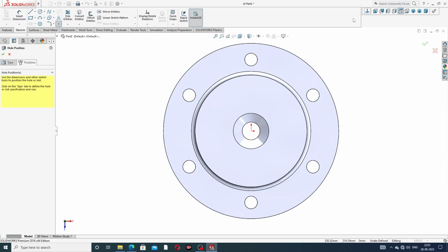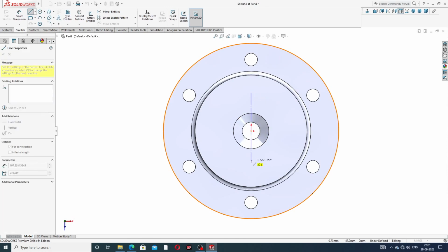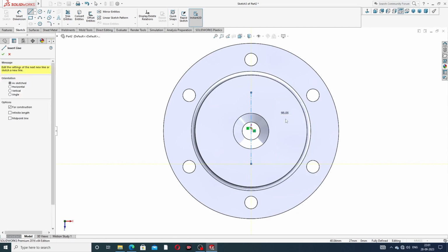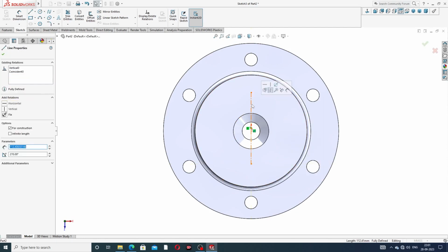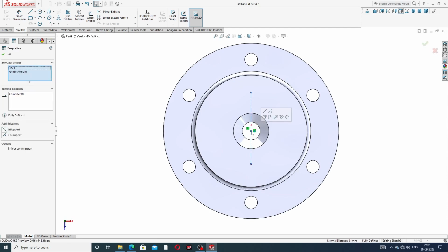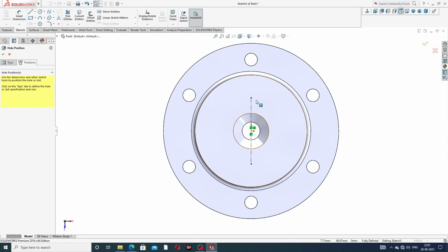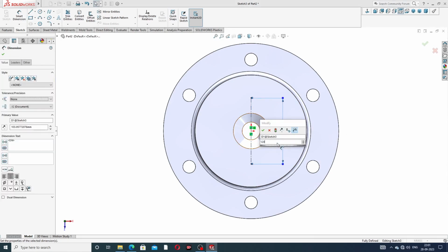This is a sketch normal. Okay, and draw a reference line. The reference line is perfectly drawn here, because this uses a mid plane. Select this line, press the Control button, select this point, and use a mid plane. Okay, and all is perfect, and the dimension is mentioned here. This is 120 millimeter. Okay, 120 millimeter is perfect.